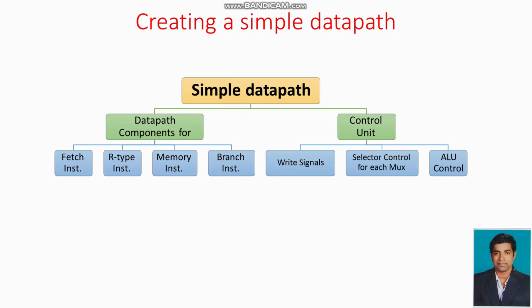Whenever different types of instructions are executed, from R-type instruction into branch instruction, we have to change the data path by using MUX. The arithmetic logic unit is performing on a particular R-type instruction, and when shifting from R-type instruction to memory instruction, we have to change the path by using MUX only, multiplexers.